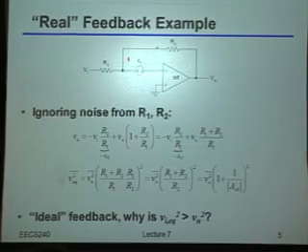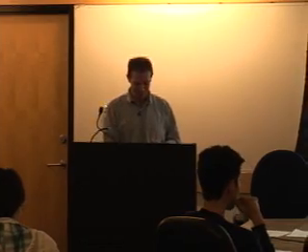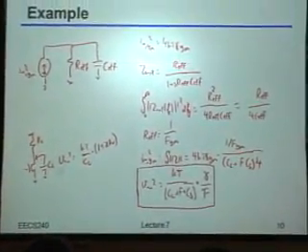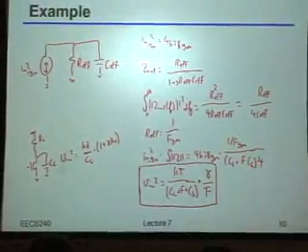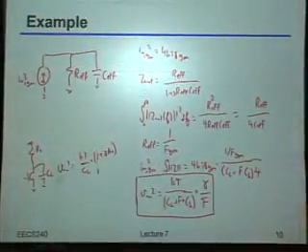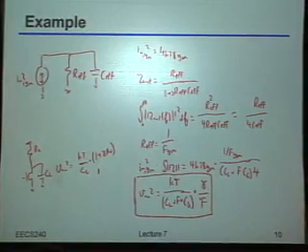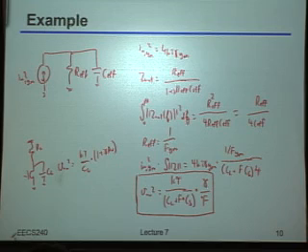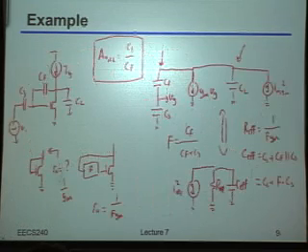Yes? Sorry, are you saying that when you just have the common amplifier, it seems like you're also paying a penalty for the load cap? Oh, that's absolutely correct. But notice the gain I would have applied to the signal would have been AV. Right? So if I input refer this, it is going to become something like kT over CL times 1 over AV squared plus gamma over AV. Right? Whereas here, what is, by the way, my gain? What did we say the gain was?